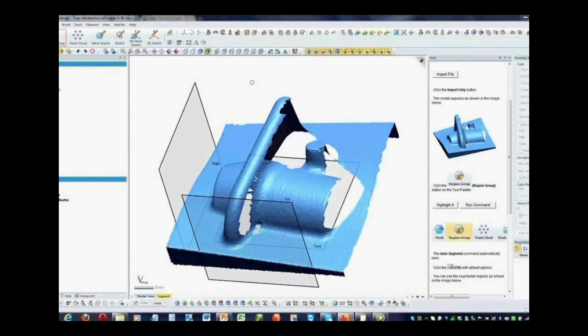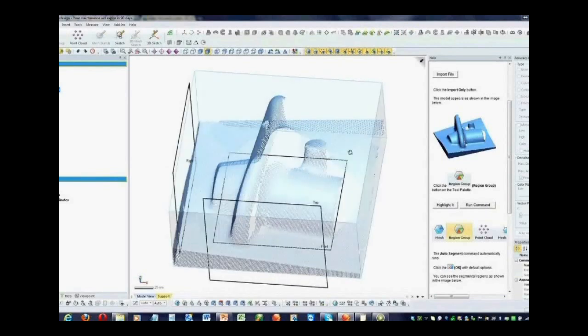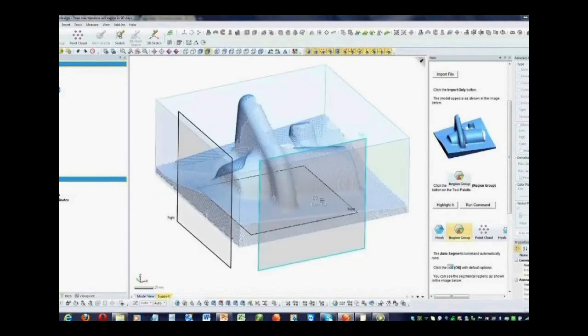And now the question, why is it that difference? Because we are using some loading, unloading process. You can right-click the mesh and click suppress. Even if the mesh is suppressed, it will still be calculated, but it's cached on the hard drive, and only the points which are necessary for visualization are shown.